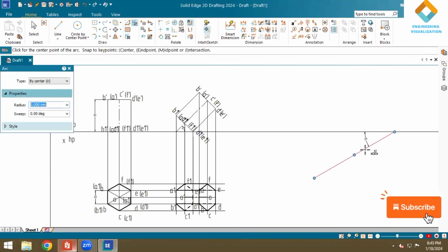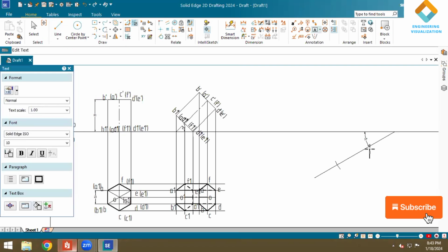So here the first arc length we should be drawing at 60 mm. Okay, need to find out the beta angle, right? So front view, first position front view, it is 60 mm. So draw an arc for a length of 60 mm, by taking one reference point. You can give this as O01.